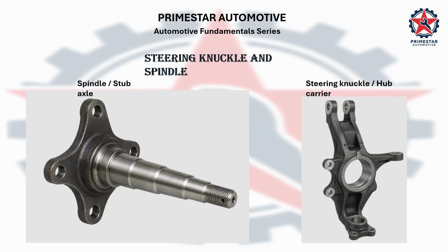Note the main identifying features of the steering knuckle and spindle. Non-driven spindle type knuckles are used for vehicles like rear-wheel drive or two-wheel drive cars, utility vehicles, and trucks. It has a solid projecting spindle or stub axle. The wheel hub and bearings rotate around the spindle. There is no front drive shaft.